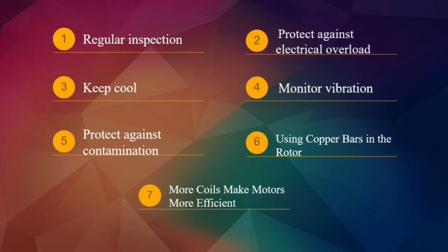A motor analyzing tool such as SKF Enlight Quick Collect is simple, low-cost option which is ideal for monitoring the vibration level and temperature of an electric motor. This can help to ensure that the motor is able to run at full efficiency and reduce the risk of premature motor failure. Furthermore, protect against contamination is one of the methods.